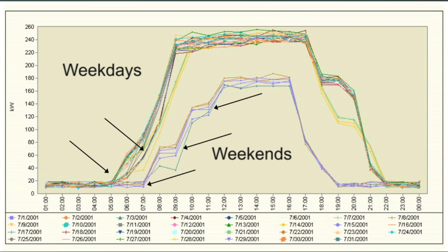In this case here, on weekdays, energy usage drops off typically after 5 o'clock. The cleaning crew comes in from 6 o'clock until 9 o'clock, and so the energy usage stays up during that period of time. There are a few days, in this case on Fridays, that the energy use drops off at 6 o'clock. In this case, the cleaning crew doesn't come in on Fridays, they come in over the weekend and clean. So the energy usage was able to be shut off a lot sooner.